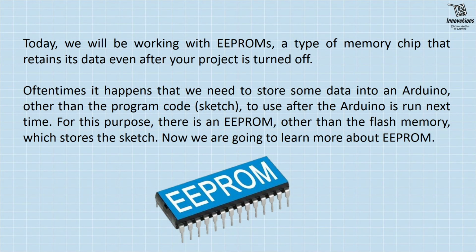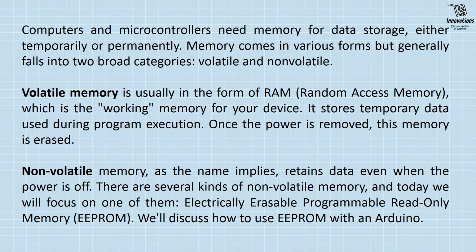Today we will be working with EEPROMs, a type of memory chip that retains its data even after your project is turned off or powered off. Oftentimes we need to store some data in an Arduino, other than the program code or sketch, to use after the Arduino is run next time. For this purpose, there is an EEPROM, other than the flash memory which stores the sketch. Now we are going to learn more about EEPROM.